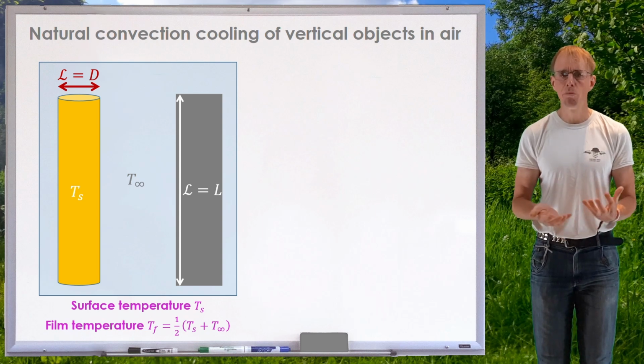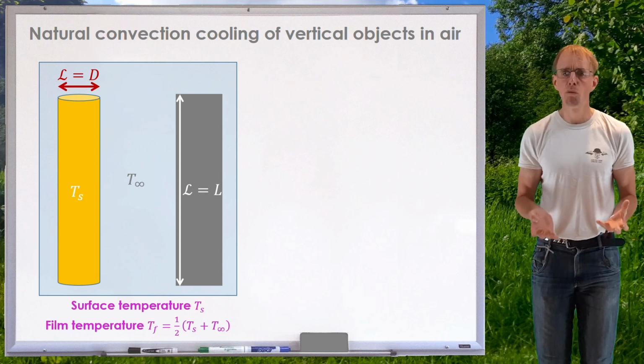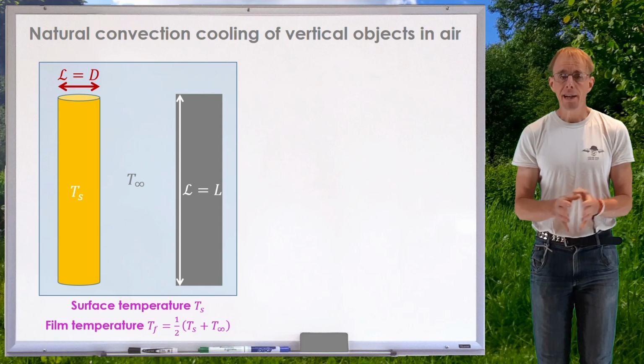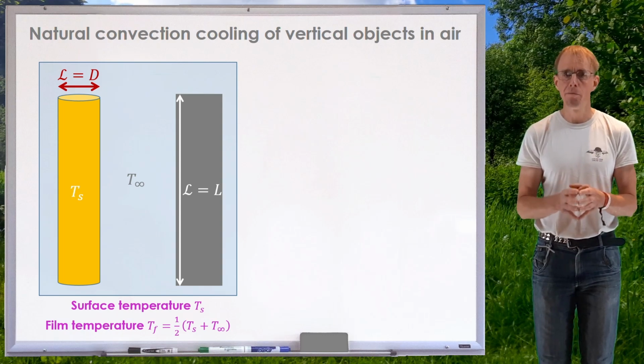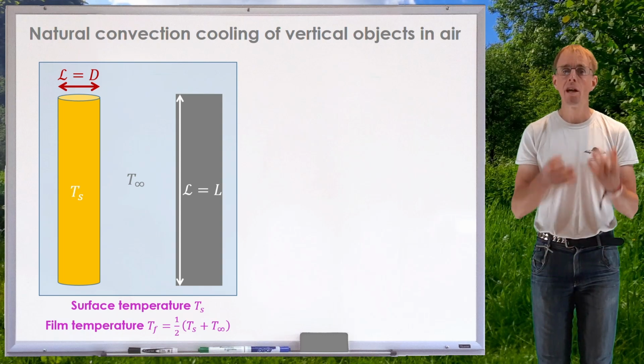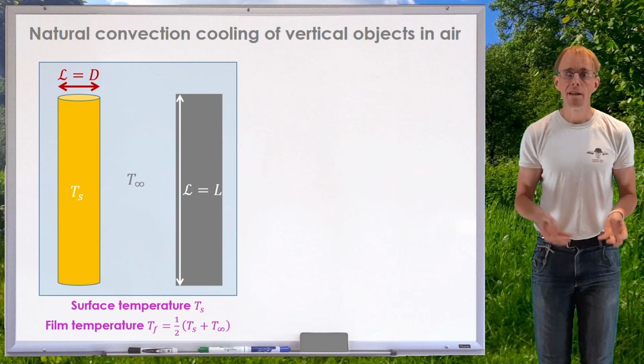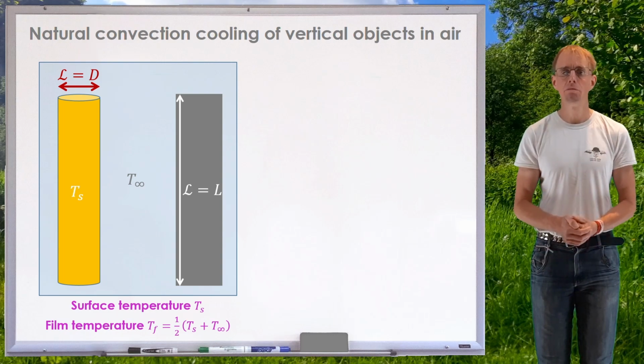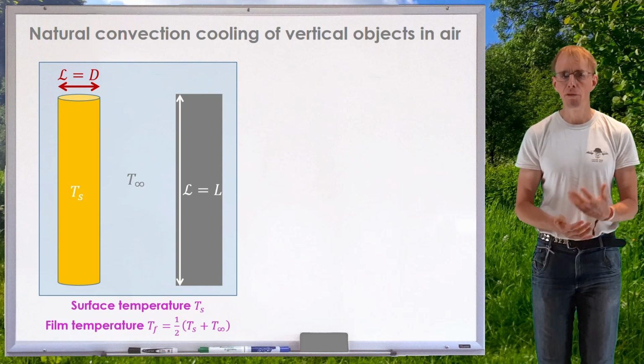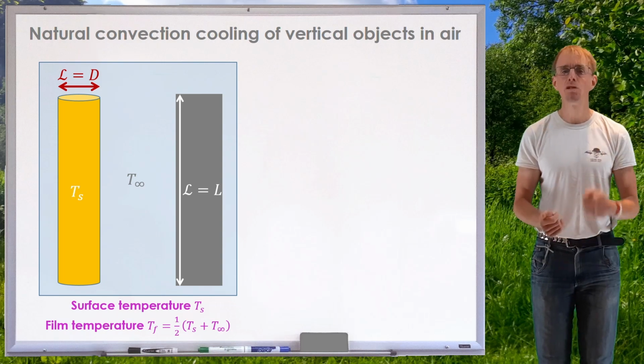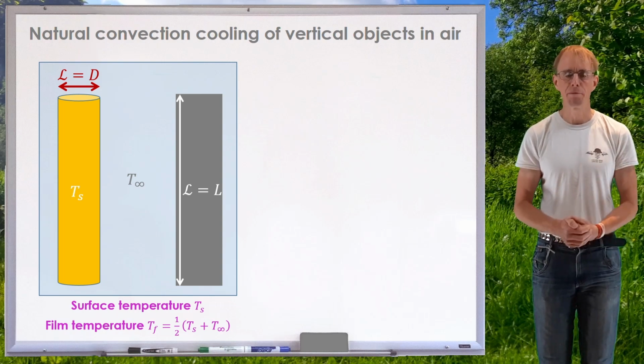As that gas warms up, it gets hot and it will rise. So the gas next to the hot object is going to warm up by conduction. That gas will rise and you'll get a naturally convective airflow or fluid flow next to the surface of the hot object. And that is what is driving the heat flow in this particular case.